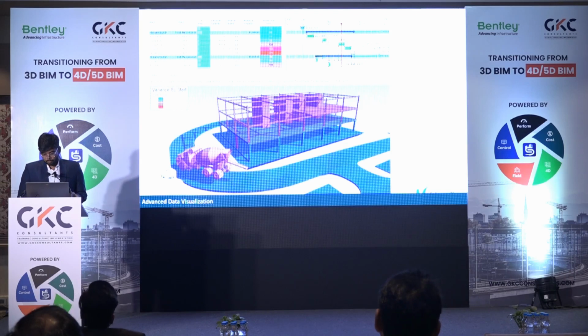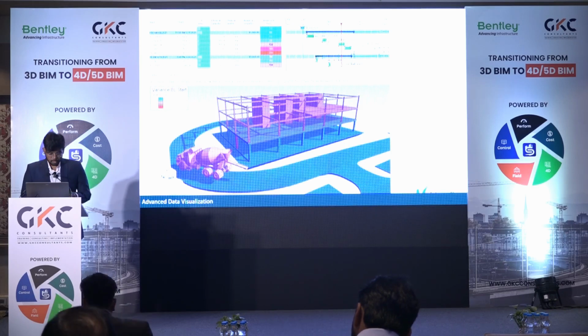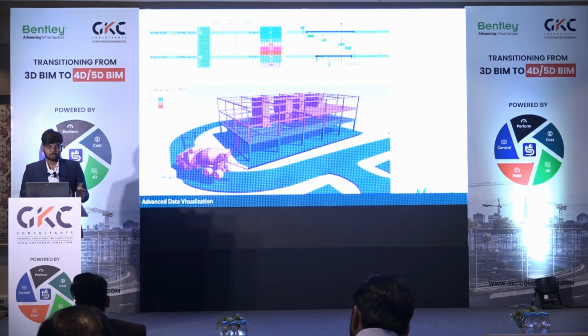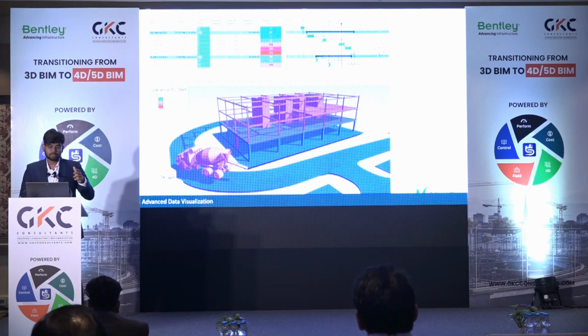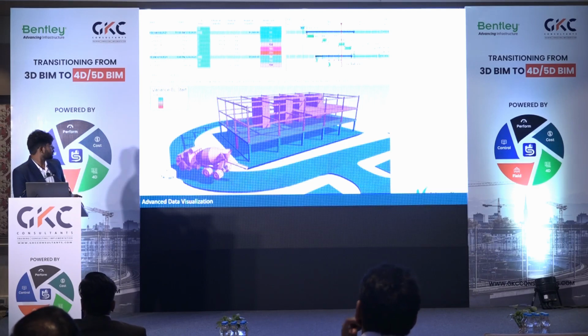Now consider that you just have this data in your bar charts. You couldn't have communicated, or questioned the way you can when you have the data imposed on top of your 4D model. Now you would see that the blue color means there is no delay, and the redder the color, the more delay there is. Now we have imposed this color on top of your 4D model, and here you can start questioning. We can see the top part is a color where we can see a 10 days delay.